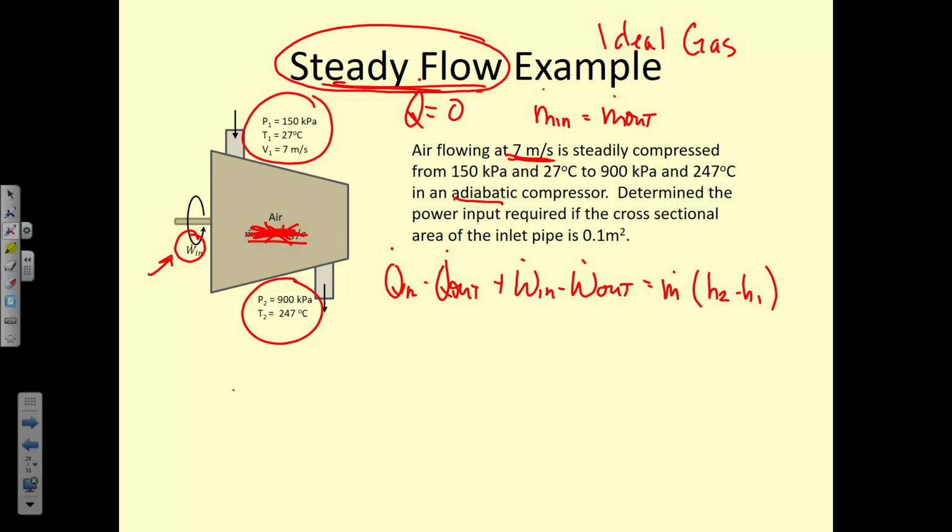Okay. So we need to find our specific volume. And how would we find that? Okay, pressure and temperature, so then we look it up in the table. Okay, we could do that, or, yeah, we could calculate it using the ideal gas law. Yeah, because it's just based on temperature, right? So it's not in that table. It would be in some other tables. If we had more extensive tables, we could look it up, but we don't.